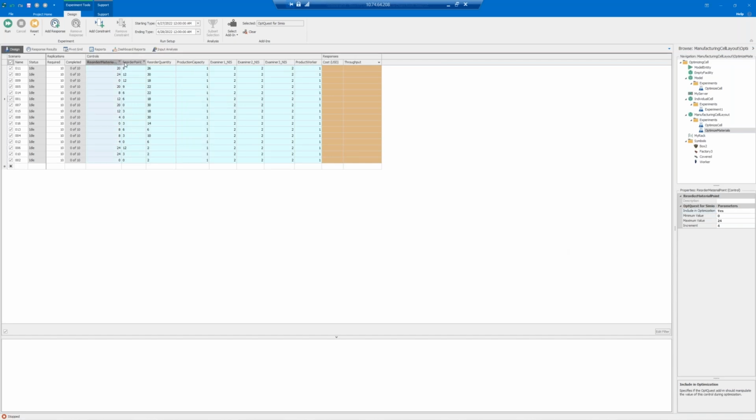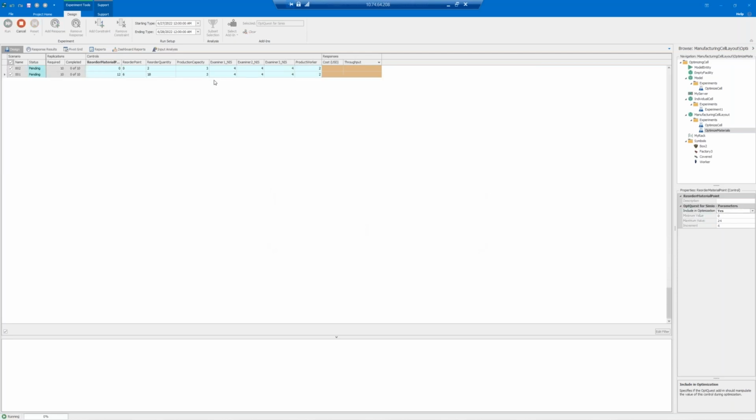Whereas all the other values that you are interested in, we're going to tell OptQuest, please optimize these. Change these up in my min-max value ranges with whatever increment I've specified and use these in my optimization. So I will just show that now. Because my values of 3, 4, and 2 for my workers and capacity are set as defaults, and I've specified to OptQuest that I don't want these included in the optimization itself, these are going to remain constant.